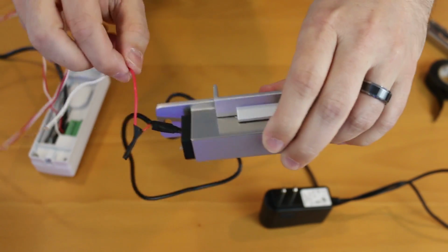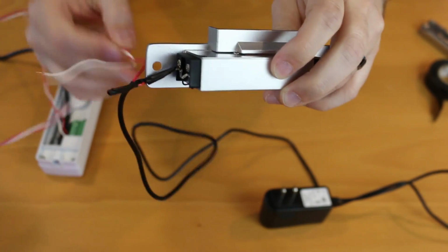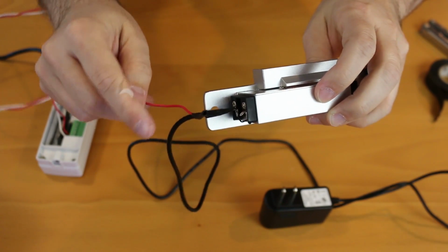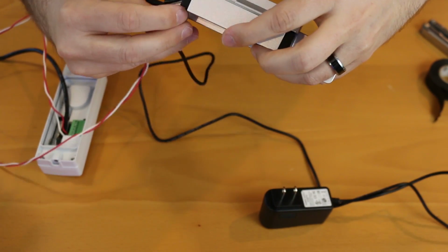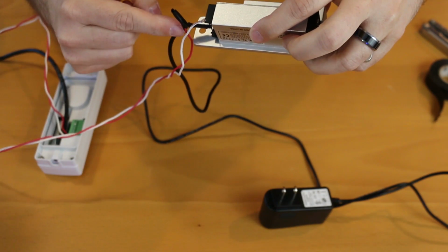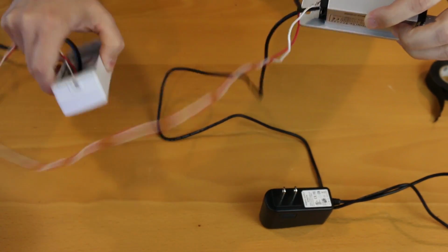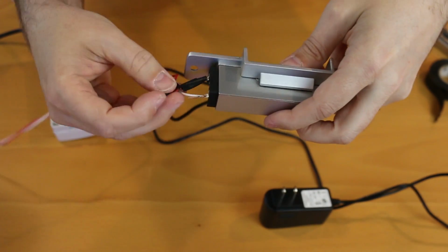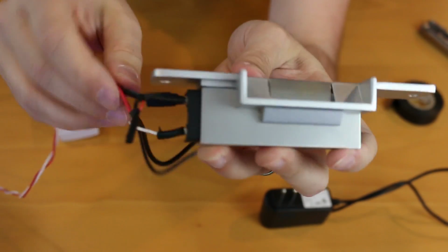We can now see that I have the red wire coming out of the power cable connected to the red doorbell wire right here. Okay, and now all we have left is our white lead, and the white lead is going to go over here on the door strike itself. So basically what we're doing is we're interrupting the red power cable with a cable that runs in and out of this door control system. Okay, so I've got that in there. So now we've got black and the white doorbell cable connected to this. Okay, there we go. So let's get you a close-up of that.